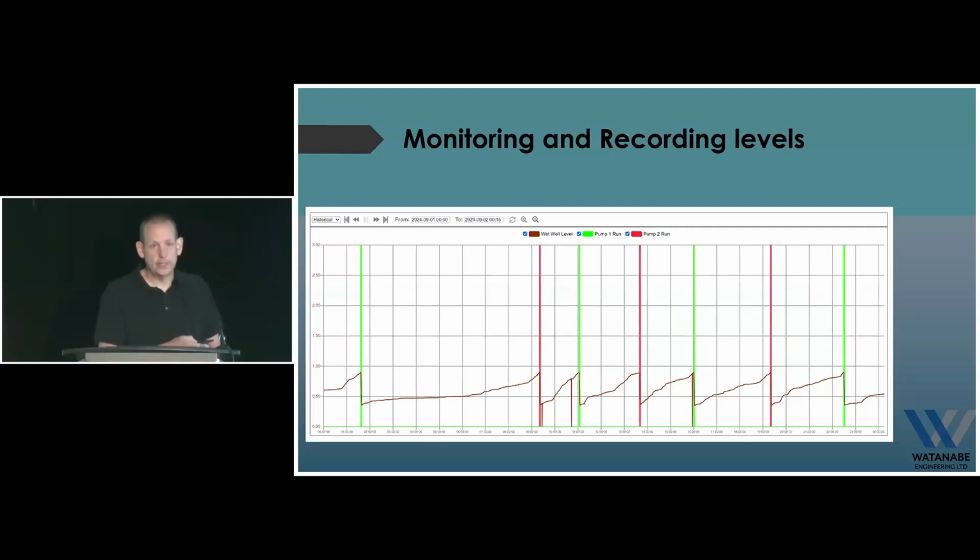You won't see that necessarily on your float-based station. Now, I know operators were really good at looking at the hour meters on our pumps and writing them down and analyzing that data to a certain degree, but that's not going to tell you the data as quickly as this is. If you've got some problems with your pumps, it might be 2 or 3 days or even a couple of weeks before you start noticing the trend differences.